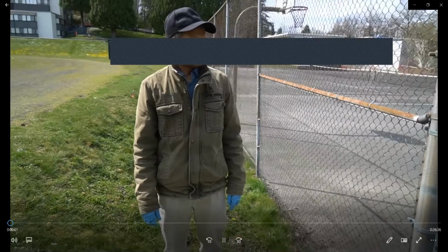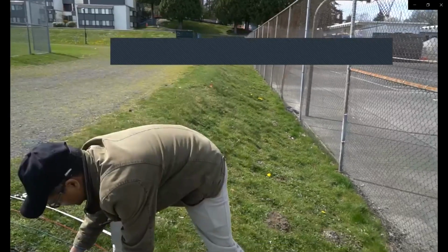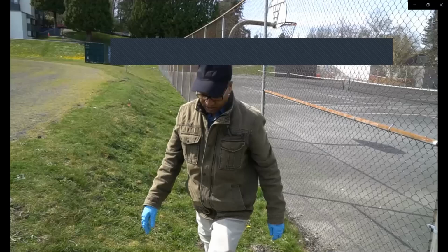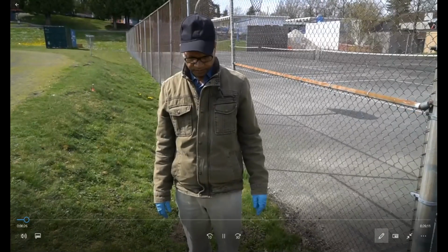Now we're going to start our third and last lab. This lab is about measuring the grid resistance, touch potential and step potential together. So grid resistance, we will measure using the method called fall-off potential. In this method, we have to select a grounding point within the substation.